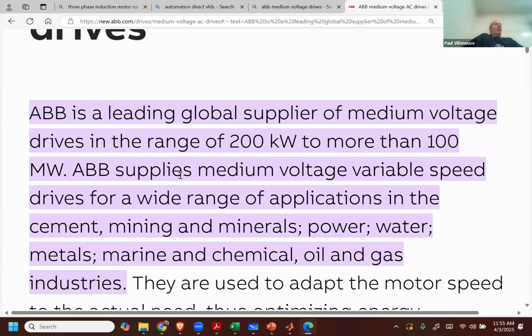How about brakes? Brakes operate a little bit differently. They operate on a vacuum. I don't know if there's a vacuum priming system for the brakes, but I don't quite know how that gets it. No, but there's the modern ones, the ABS module has an electric pump in it to pressure to assist the pedal. Yeah, pressurize the system with the brake fluid. And why do they do that? Because if you're not running the brakes, why would you run a pump to help with vacuum when you're not applying the brakes? Well, there's also an issue with modern cars that the manifold vacuum is not really enough to operate them anymore.